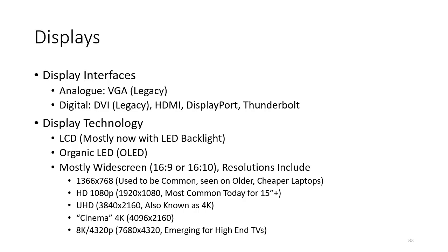The displays themselves can use a variety of technology. The most common today is LCD, liquid crystal display, commonly with an LED backlight. In the early days of LCDs, we used a different sort of backlight which had a limited life, but LEDs can last a lot longer. And also, if you're looking at consumer grade technology, you can have different zones of LEDs behind the screen, and that can improve the contrast, because you can turn those LEDs off, so that makes that part of the screen darker.